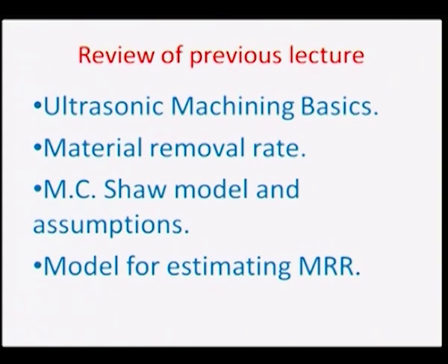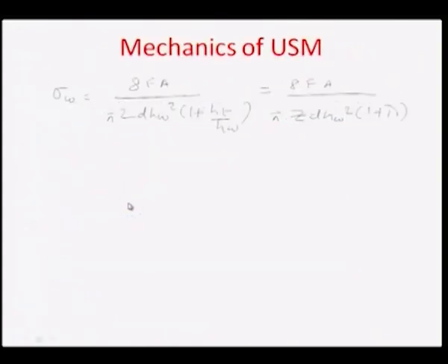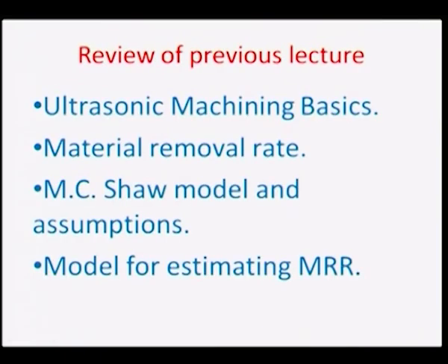We also investigated this M.C. Shaw's model for predictions of material removal, and made some assumptions in this model, where we talked about how the abrasive grain should be treated as spherical, and also as if there are many grains between the tool head and the workpiece.